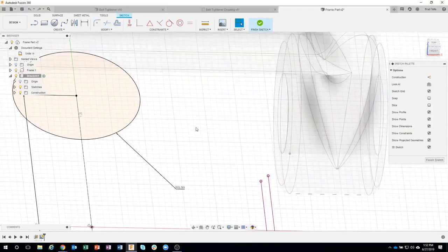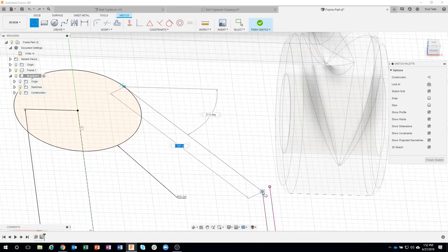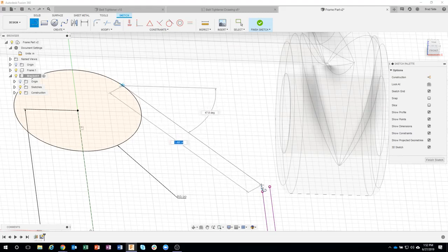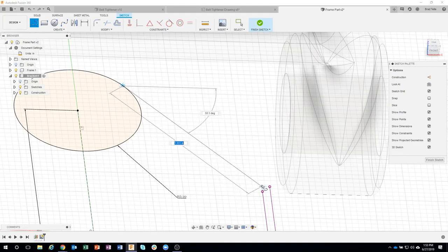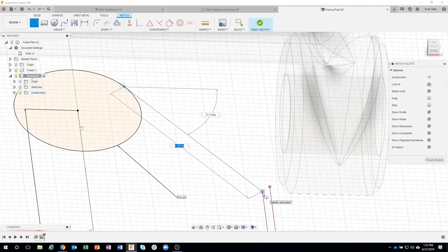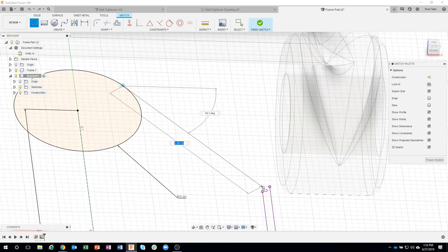Let's do that. I'll say line, hold down my Shift key, come across. So I need to be here, but I need to be up a little bit, but you'll notice it doesn't know how far up it needs to go. Well, all I have to do is hover for about 1/2 second, and now you can see it's in line with that other dot. And then I'm just going to come back here, and it's kind of hard to see because my cursor is covering it, but there's now 2 dashed lines, and it's basically saying you're lined up with this dot and you're lined up with that dot. Okay, so all you have to do is hover for about 1/2 second, and then I'll just go ahead and click that.